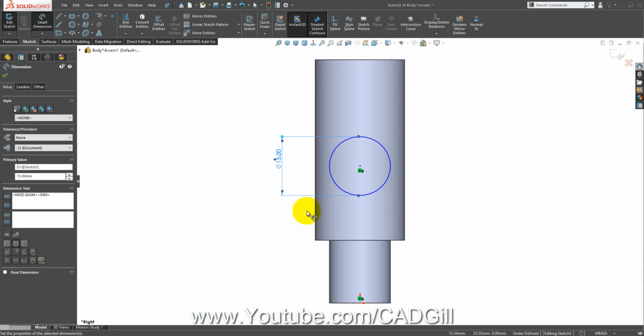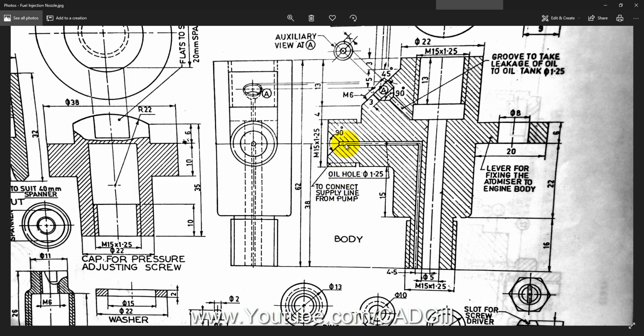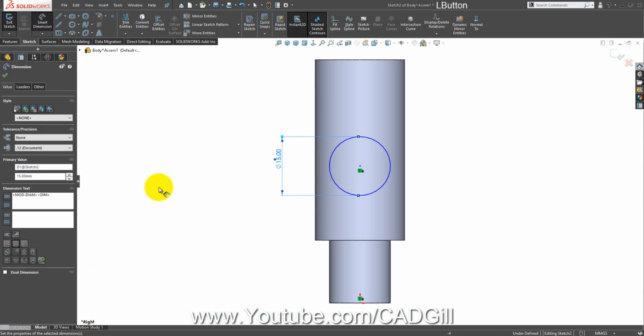Okay, the center distance is there, there should be some center distance here. Okay, they have given it differently. 13 plus 4, 17 plus 7.5. We can calculate it that way, but if you ask me, we never assume, we never take center distance for a tap. Okay, for threads. Okay, we can use this 38 here. This is given directly here, so let's use 38 mm.